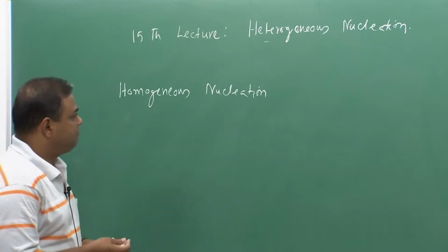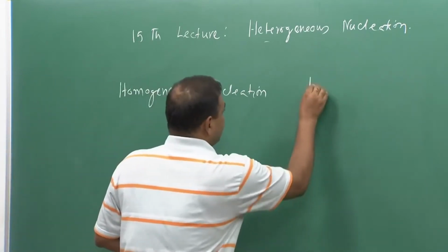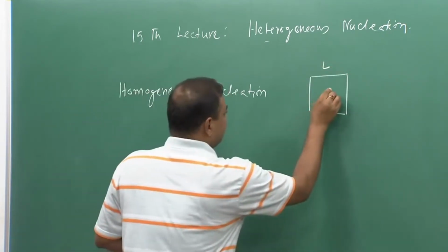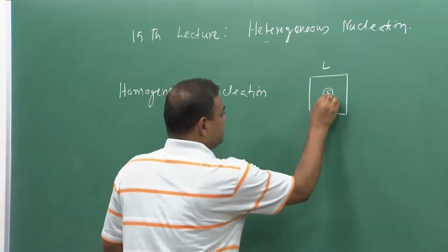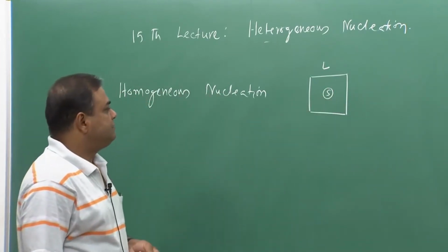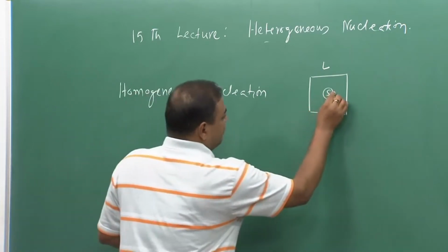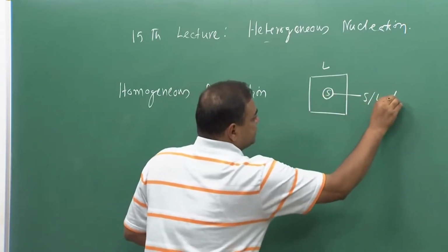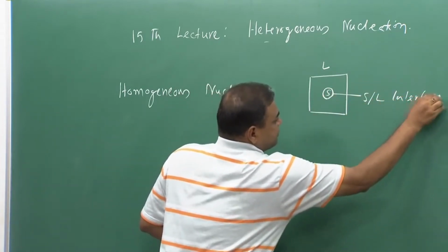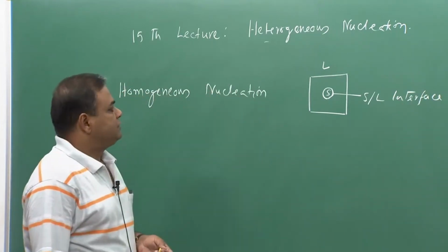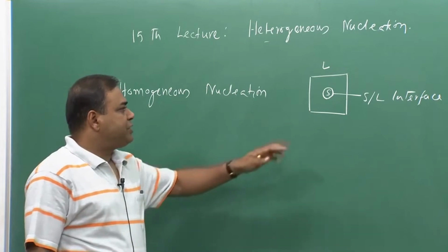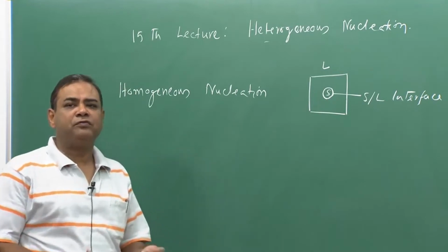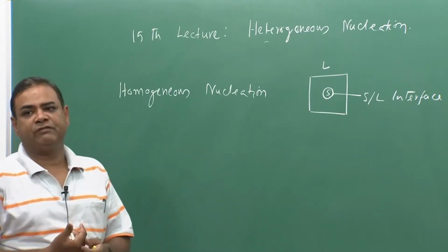So, that makes it clear that whatever discussion we had, that means in case of liquid volume, if we have a formation of a solid, that time this solid liquid interface is the only interface. This is the only interface which is solid liquid interface. And the total energy requirement for this interface creation is coming from the volume free energy change, which is the thermal factor.